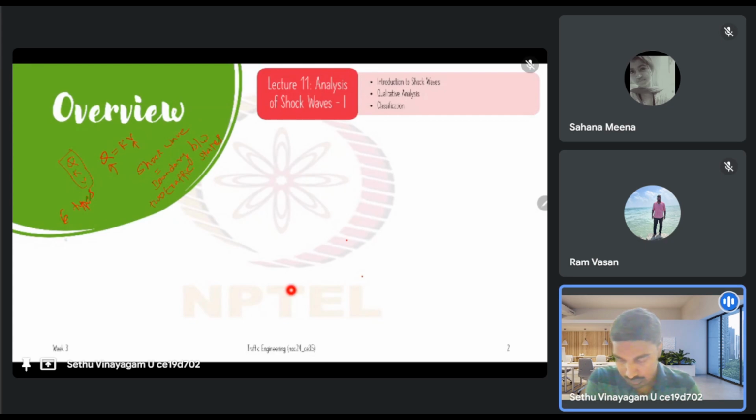So these are frontal stationary. Then we have forward forming. Then we have forward recovery. Then we have backward forming. We have backward recovery. And then we have rear stationary. Right, so these are the six different types of shock waves, right?